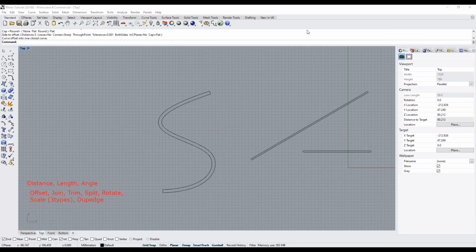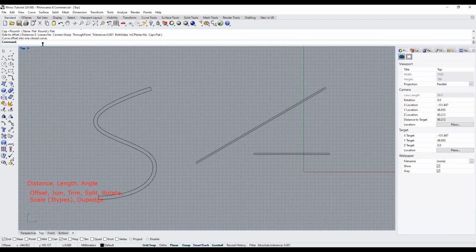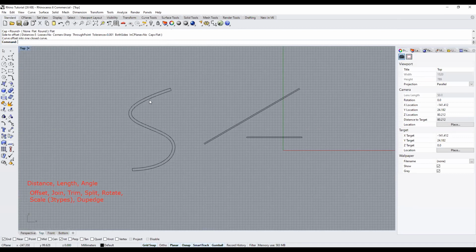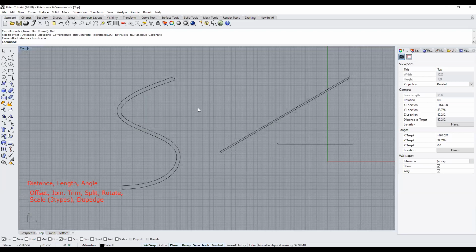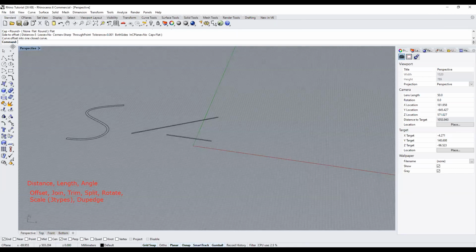Curve literally just means line. But the reason why I say curve is because a lot of the commands you have on Rhino say it's a curve, it's not a line. So you'll see later, but there are some commands that turn the curve into a poly surface. And if you type in line, nothing will show up. The solids usually just means poly surfaces because they're made out of many surfaces altogether. But I'll explain that later on.